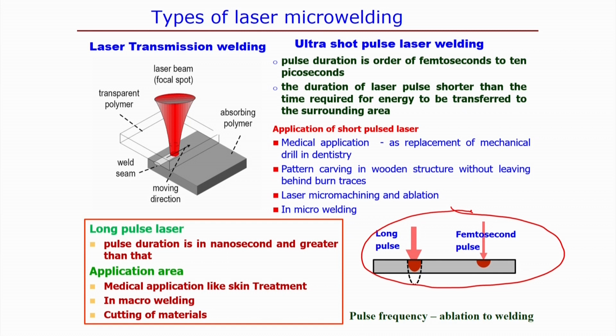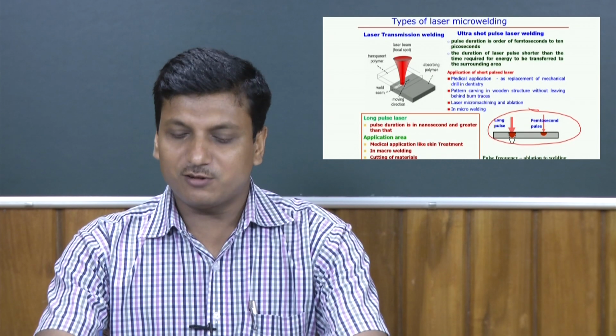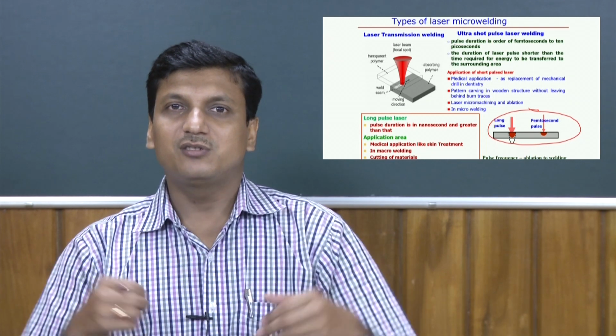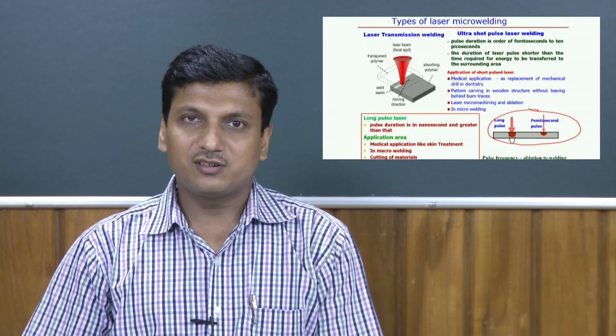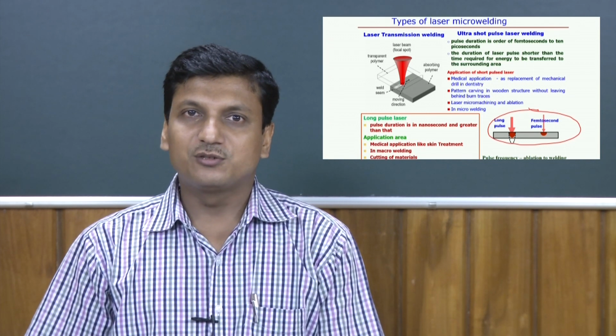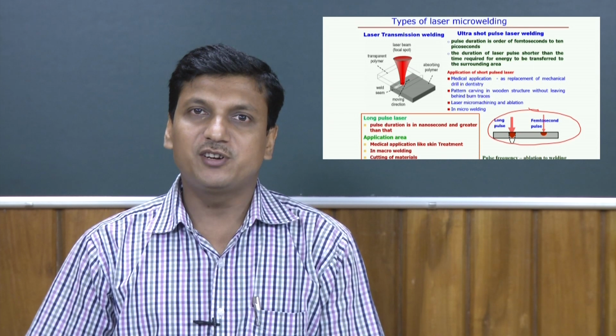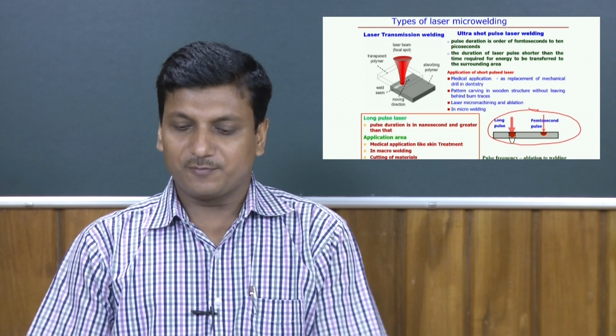Normally, if pulse frequency is very low, then it is suitable for laser ablation of materials, because low frequency means that within a small time gap there is an application of a continuous pulse energy. That energy ablates the material without affecting the surrounding material.